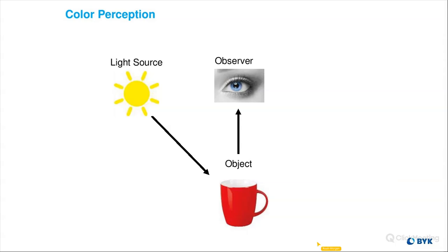Again, we have a great presentation on this one too, where we go over when to use it, why to use it, and how to use it. A sphere is essentially, if you can imagine a white sphere that's coated in white, and it sits over top of a sample. As you take a measurement, your light is not hitting the sample directly. It's actually diffused light. In 45-0 geometries like this, a direct light source hits the object that we're trying to measure, whereas in a sphere instrument, you're using diffused light.